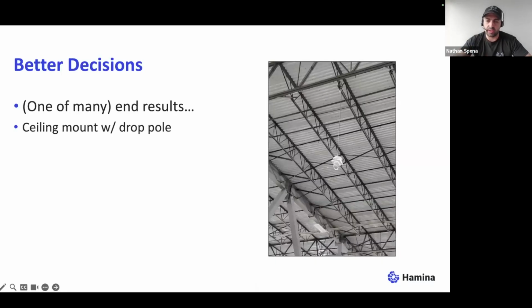So this here was at the edge of the aisles. We had a large square section, probably about 20 meters wide and about 100 meters long, towards the edge of the aisle. So we ran these patch antennas off these threaded rods here. Obviously, when you're doing this, make sure that the customer's not using a forklift or anything along those lines, which could impact your design and your implementation. In this case, the forklifts weren't running within this area, which allowed us to get, I think, this height of the ceiling was about 15 meters.